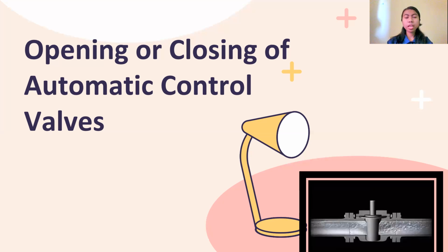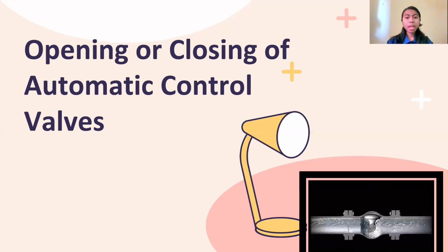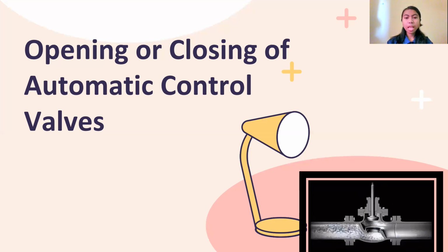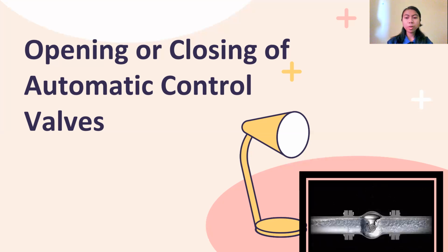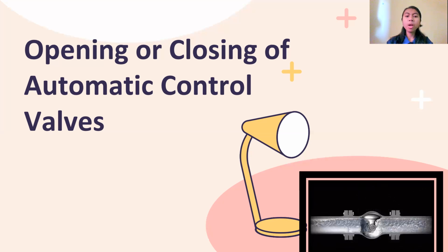Valve positioners are used to ensure the valve attains the desired degree of opening. Air-actuated valves are commonly used because of their simplicity, as they only require a compressed air supply, whereas electric-operated valves require additional cabling and switchgear. And hydraulic-actuated valves require high pressure supply and return lines for the hydraulic fluid.